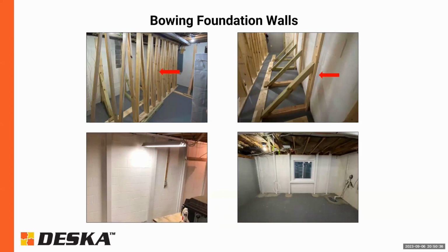So at all areas where the beam goes into the concrete, there are clear cover requirements. It has to be surrounded by typically about 3 inches of concrete. The minimum is about two, but we always over design everything. Essentially, we use 3 inches of concrete to ensure that no water is getting to the steel beams. And in this particular case, a drainage system was actually installed at the same time with a vapor barrier to protect the beams as well. So the short answer is yes, but the proper precautions need to be taken.